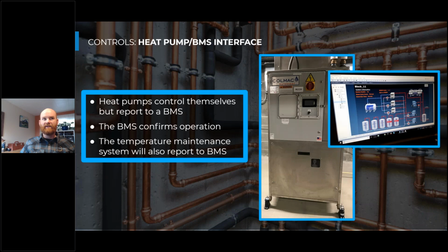But there are some advantages of tying this into our BMS interface to get that feedback, and that's what's really happening here. And this is typically a little bit less cost than the full BMS interface and still relies on the heat pump to control itself based on a temperature in the storage tank. But in this BMS system, we can trend the outlet water temperature, the various storage tank temperatures, the run times, and a lot more data, which can be really influential to optimizing our systems and doing preventative maintenance on this type of system.